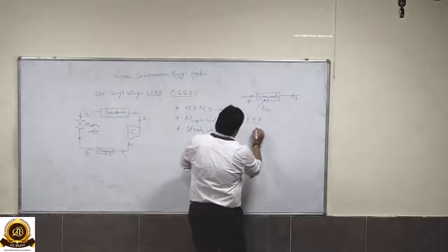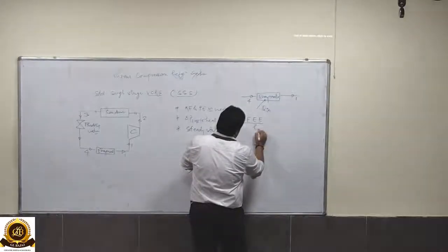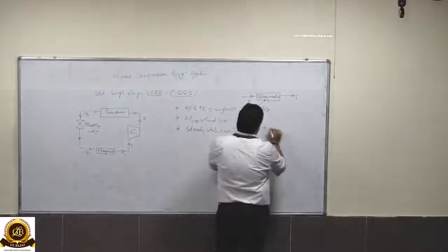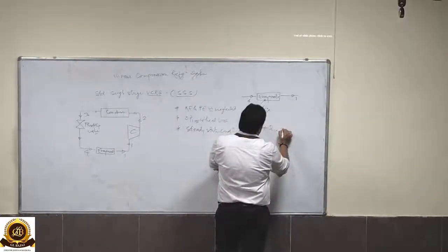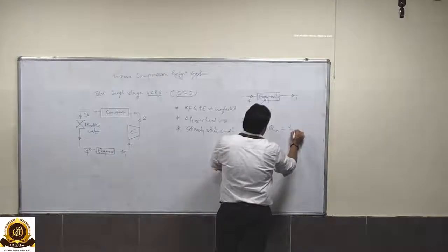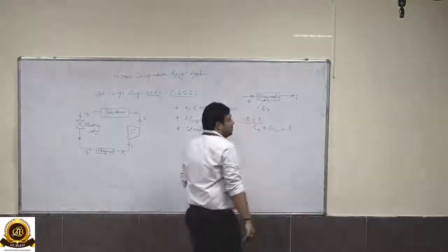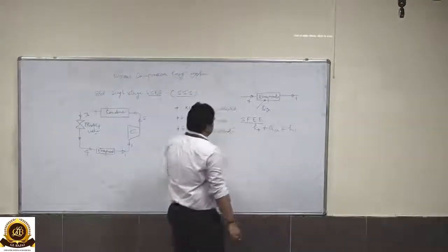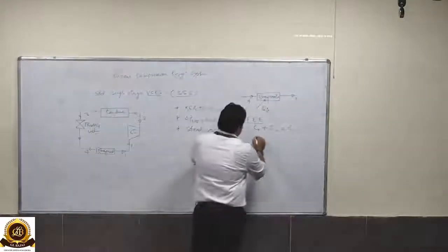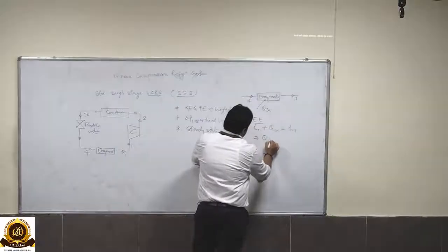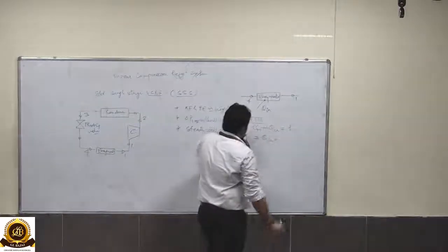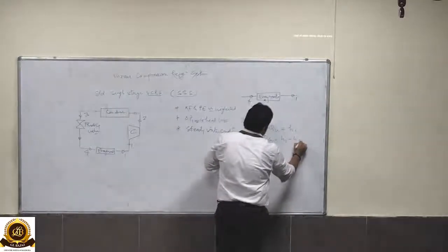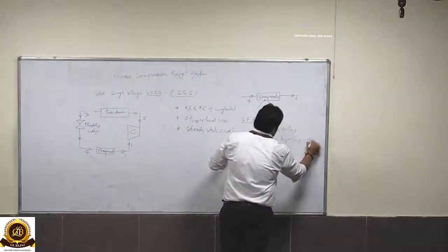So, if we apply the steady flow energy equation, we have H4 plus Q in is equal to H1, because there is no work transfer, no loss is considered, and kinetic and potential energy are already neglected. So heat addition into the evaporator is given by the formula H1 minus H4. That is again the refrigeration effect.